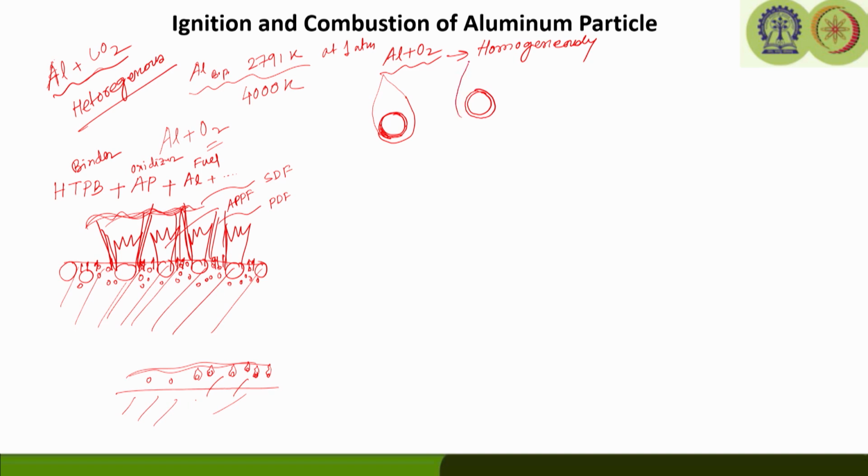As the flame goes on, the aluminum particle is burning, and some of the oxides are going to merge with this native oxide cap and increase the thickness here. Now, due to the surface tension force, it is going to pull off the oxide together with the oxide cap, and it is going to separate from the molten particle. So, this is your aluminum, the temperature is high enough, so the aluminum becomes molten aluminum. The cap is actually separating out near the bottom.